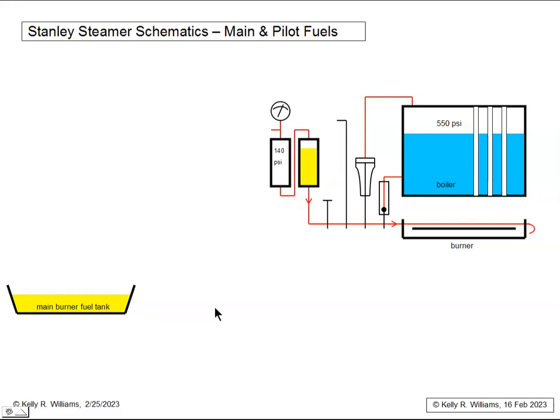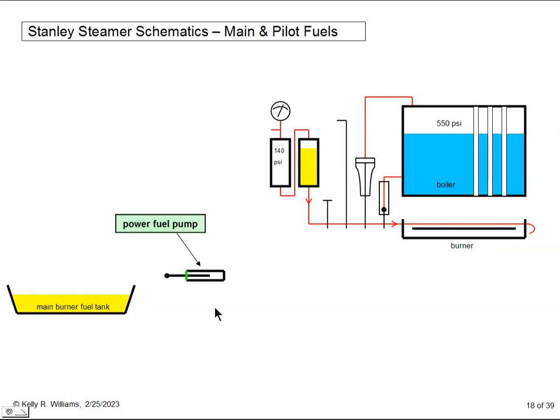Well, we have to move the fuel from the supply tank to the pressure tank, so we need a pump. This is a plunger pump, not a piston pump, so the plunger doesn't make contact with the inside wall of the pump. The packing, in green here, seals the plunger's movement. When the plunger is pulled outward, it creates suction here and draws fluid in. When it's pushed back in, it creates pressure here and forces fluid out. The pump is connected directly to the engine by a long rod, so that whenever the car is in motion, the pump is moving fluid.